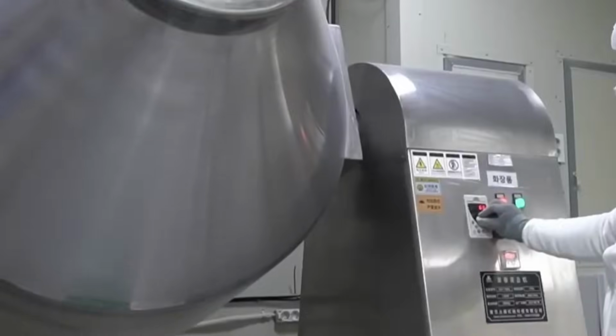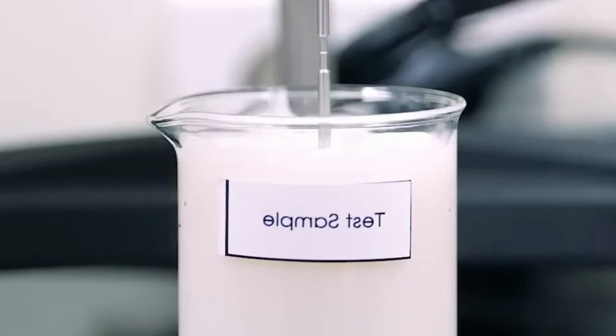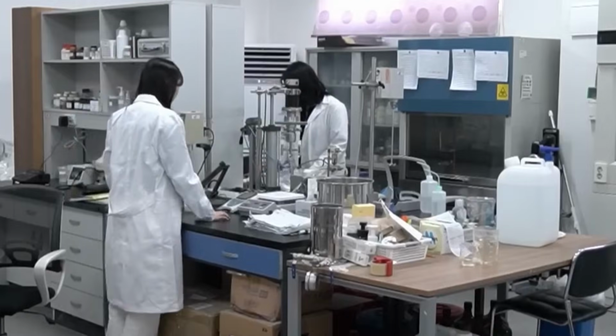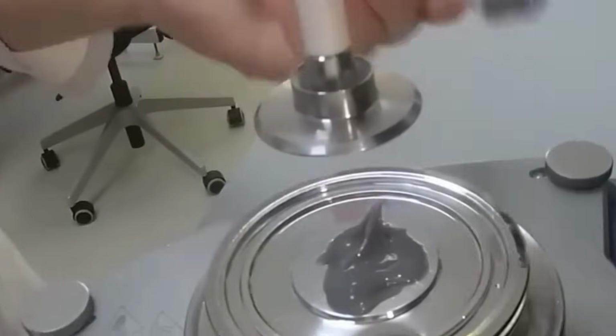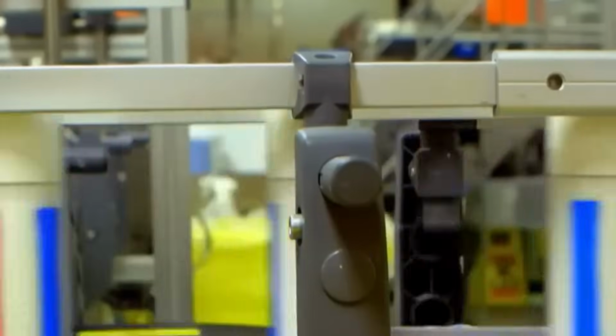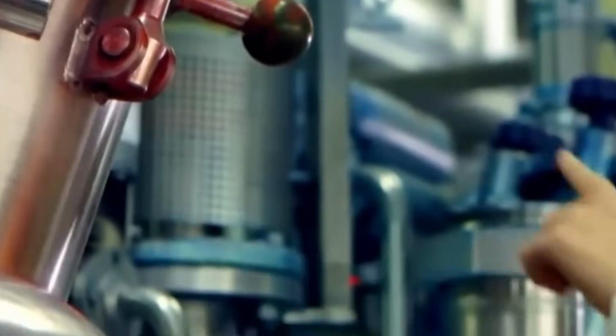Full pallets are stretch wrapped using rotating ring or arm wrappers. The film tension and overlap are adjustable to prevent compression of cartons while ensuring unit load integrity. Pallets are labeled on two sides with shipping and tracking information. Barcode scanners verify label accuracy and update inventory systems. Pallets are then transferred to staging zones for warehousing or direct shipment.